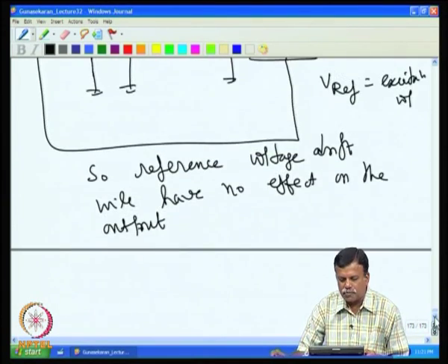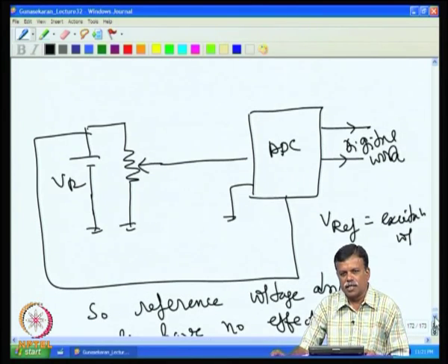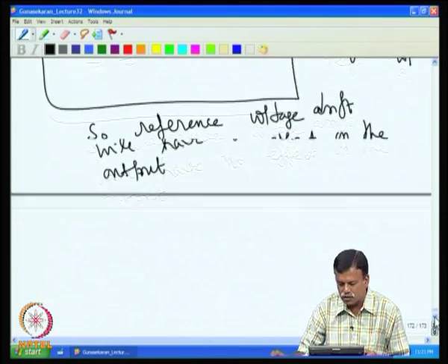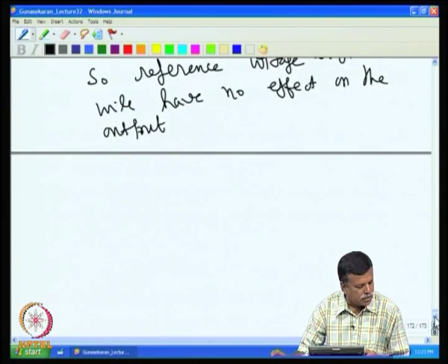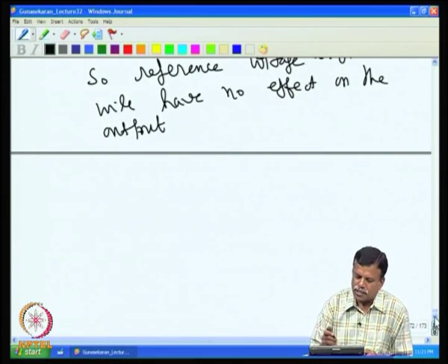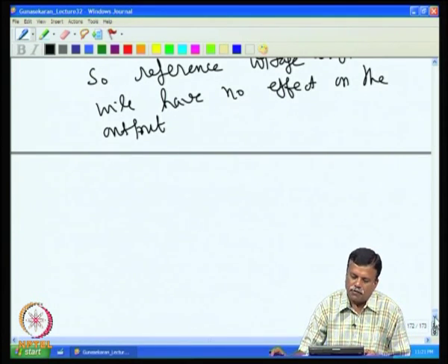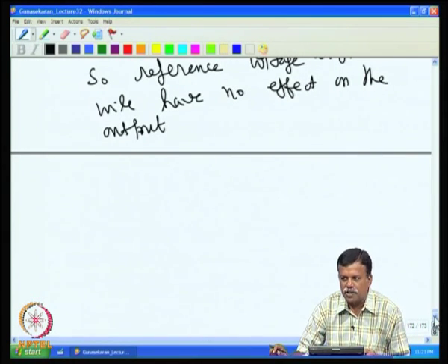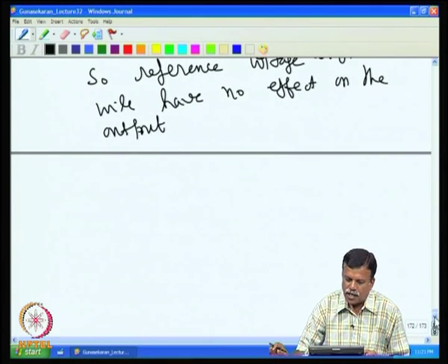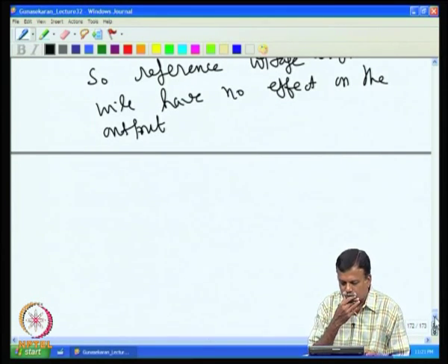Now, we have processor based A to D converters, which are extensively used in the industry. So, one has to worry about what errors are involved, because most believe that if it is an 8-bit converter, you will get 8-bit accuracy. That is no more true. So, when you are using a processor based system with an inbuilt ADC, one has to clearly verify from the data sheet the actual error associated with the particular converter.